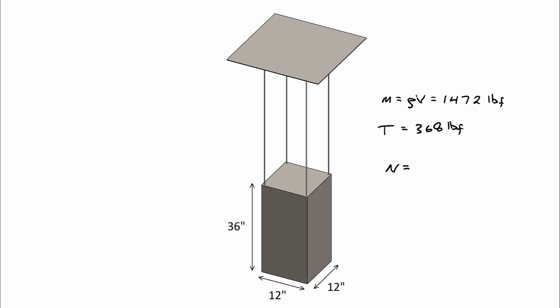Okay. So if it was at 368 pounds, we needed to be able to withstand 3 times as much because we're looking at a factor of safety of 3. How do we define failure? Absolutely. So when we talk about defining failure here, we usually mean that the rod would start to permanently deform or yield under the load.